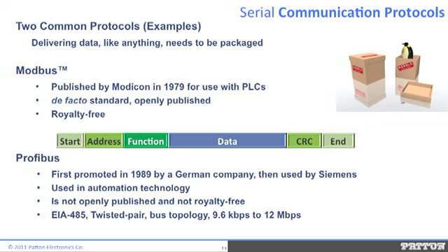There are numerous synonyms used in data communications for packaging. You may have heard of encapsulation, or frames, or perhaps some others. The Modbus serial communication protocol was published by Modicon in 1979 for use with PLCs. It became a de facto standard, was openly published, and offered royalty-free. The framing or encapsulation is simple.